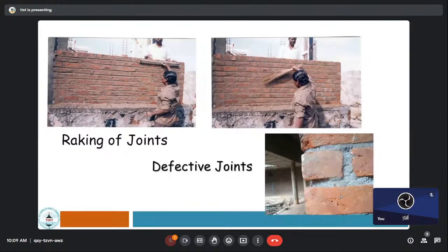Plaster is normally measured in square meter, so thickness does not have importance over there. The less you can make it, the better. For adhering such a lesser thickness, we require some vacant gaps. That's what raking is done for.